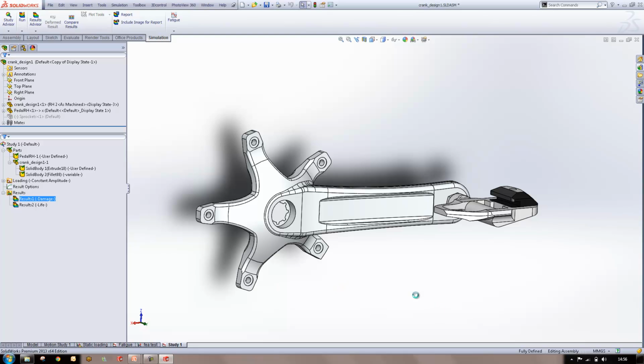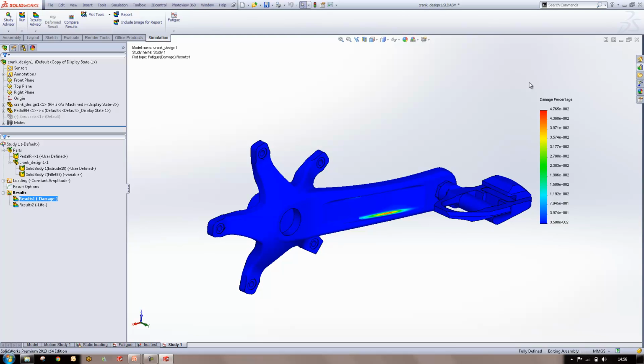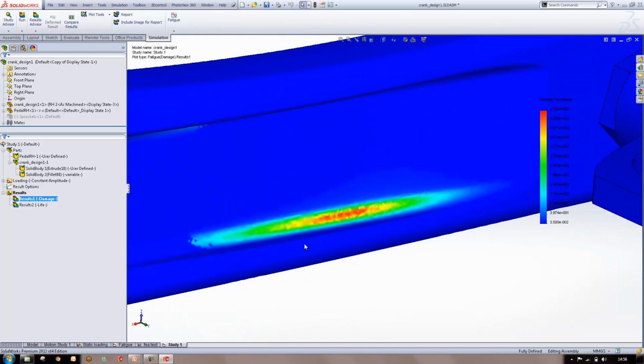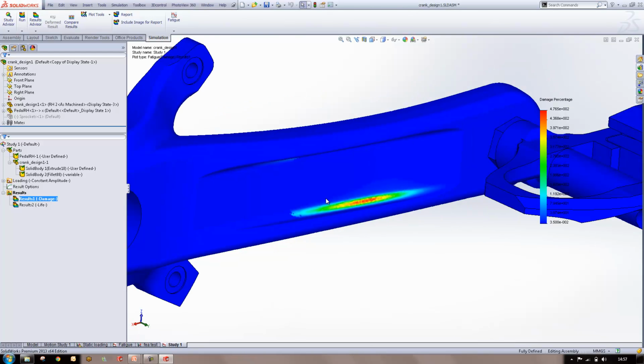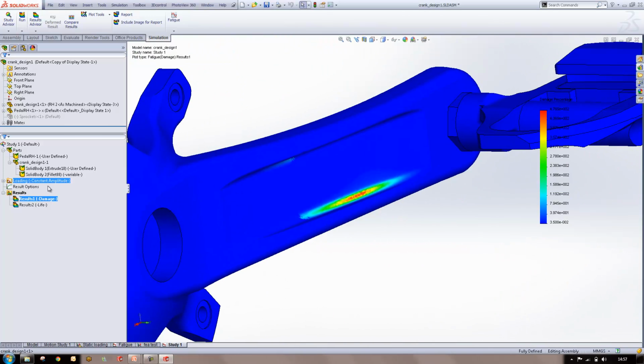And so, for example, in this case, after 7 million cycles, we can have a look at the damage that we've got there. So our damage percentile value is currently sitting at 475, which is essentially a failure. So after 7 million cycles, we have long surpassed failure. And in this case, you can see highlighted there where our highest damage is and hence where our lowest life is.